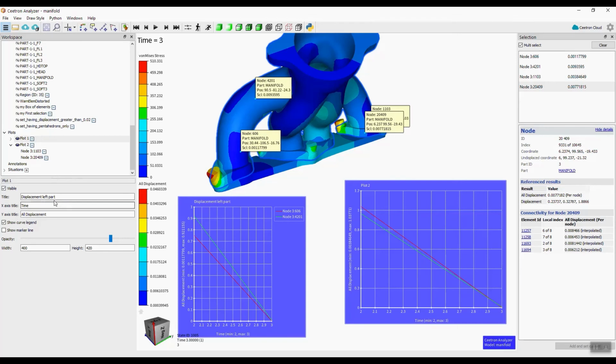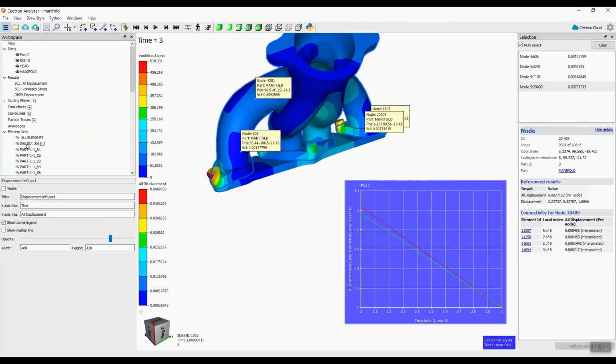Changes to properties, of course, apply to the plot selected in the feature tree. Note that the visibility of a plot is either controlled in the Properties pane by double-clicking on it in the tree, by clicking on the eye icon at its left, or finally through a right-click on the tree item. This is not shown here, but if you wish to configure a specific curve of the plot, simply select it in the feature tree and specify your preferred curve title and color.